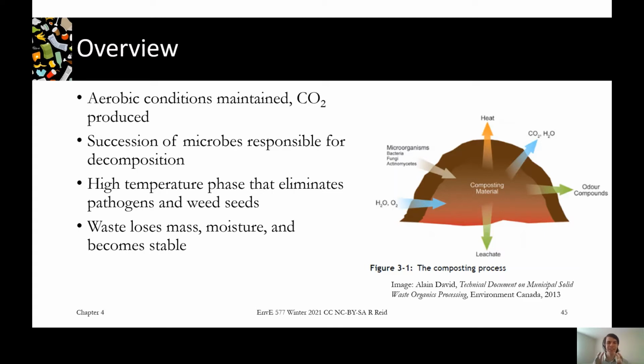We have this characteristic high temperature produced by composting. So composting, as I've mentioned a few times, has a lot more energy thermodynamically to work with than AD. So it ends up producing a lot of heat in the process itself. That helps dry the material out, and it helps eliminate pathogens and weed seeds, which produces a high quality material that you can't necessarily get from AD. Thermophilic AD, you get a little bit, but you don't get that drying effect as well.